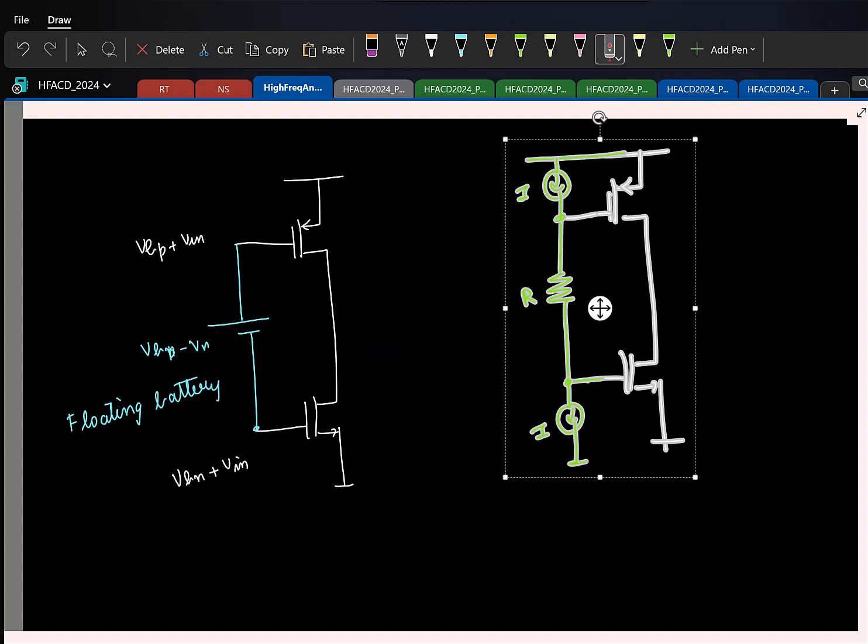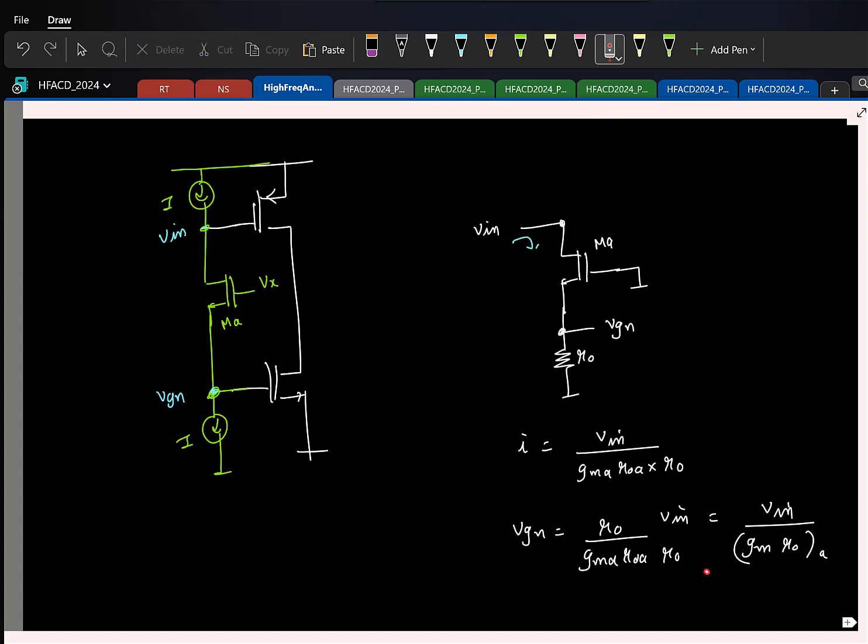With respect to small signals, you want the resistance looking in between these two terminals to be 0, as small as possible. But now that is not small because you have gone and connected the drain of the transistor. So which means this will be very high impedance, right? And that's what is causing the issue. So to reduce the impedance, I should connect something here, right? And that should reduce the impedance.